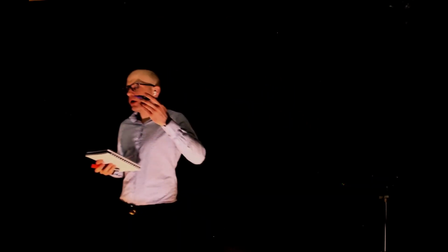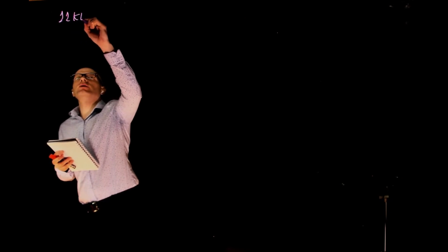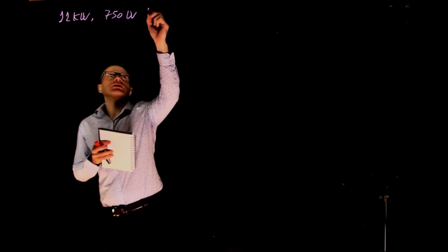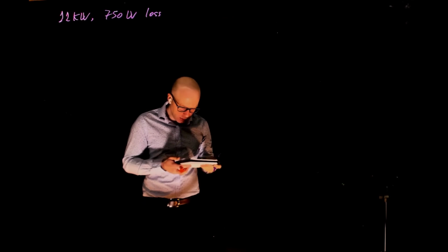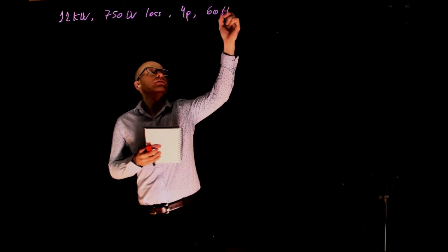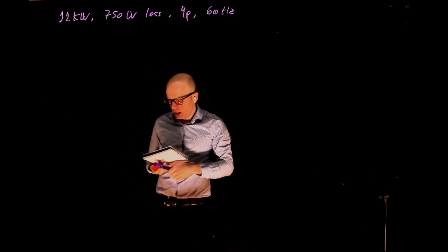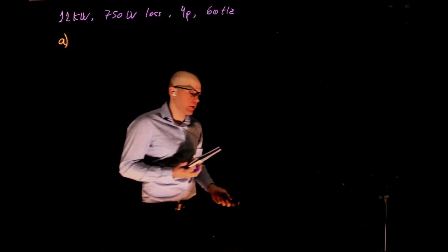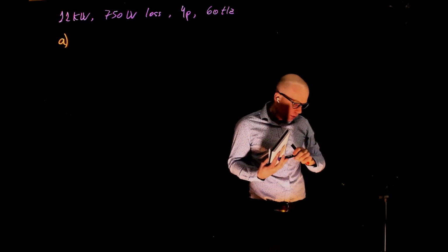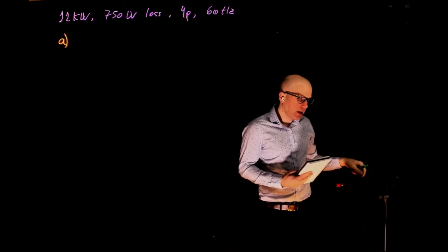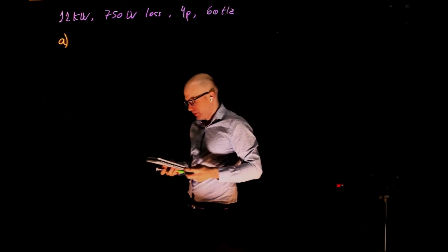Let's summarize here what we have. We have an 11 kilowatt motor, and we have 750 watts in losses. What else is important here? We have a 4-pole, 60 hertz. Question A, what is the mechanical power developed in the motor? Any ideas? What is the mechanical power in the rotor?